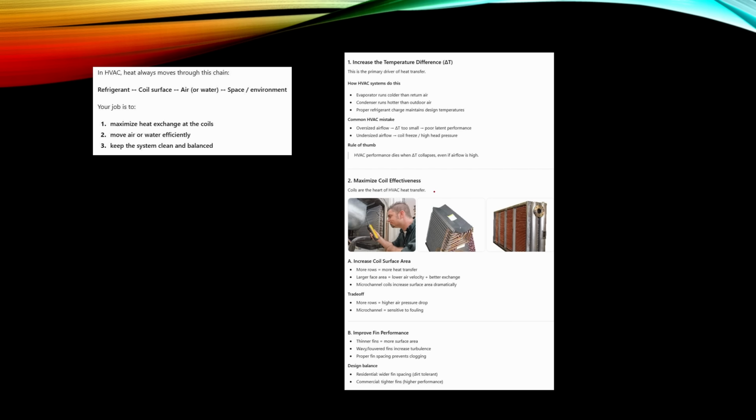Also there are many challenges if these are big units. Then we need to guarantee that the airflow to this unit is even. Maybe we need some guide vanes in the duct before this unit. Here are some guides on how we can get a more effective unit. One way to increase the efficiency of this kind of coil heat transfer unit is to add fins.